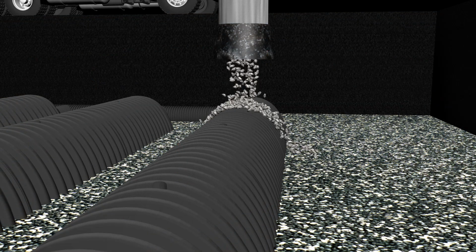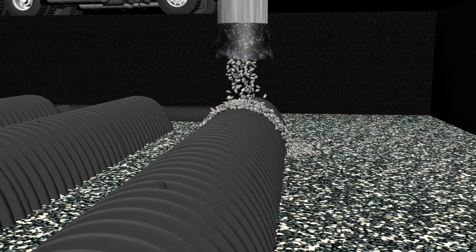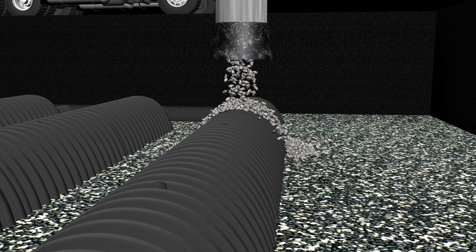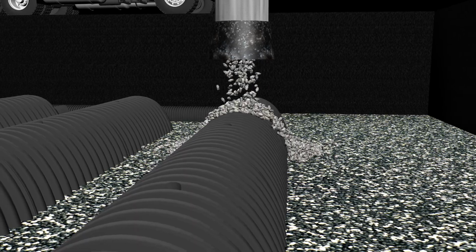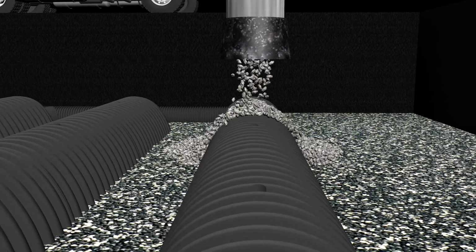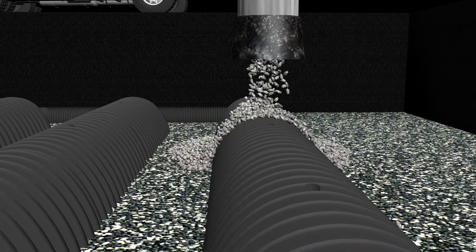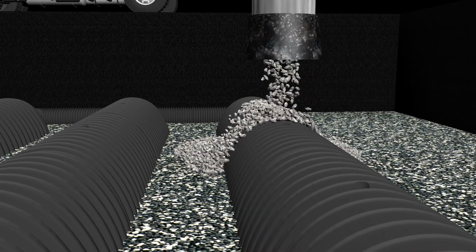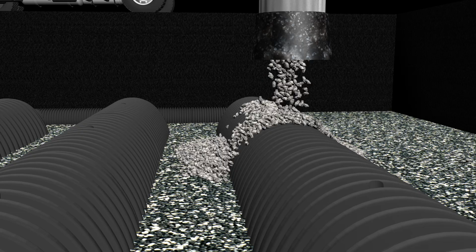An initial stone weighting of the chambers will help secure the chambers while the embedment begins. Carefully dumping stone directly on top of the chambers will keep them weighted as stone slides down each side to form an anchor. Embedment is achieved using a stone conveyor shooter system that can be stationed off the chamber bed during the entire embedment operation.